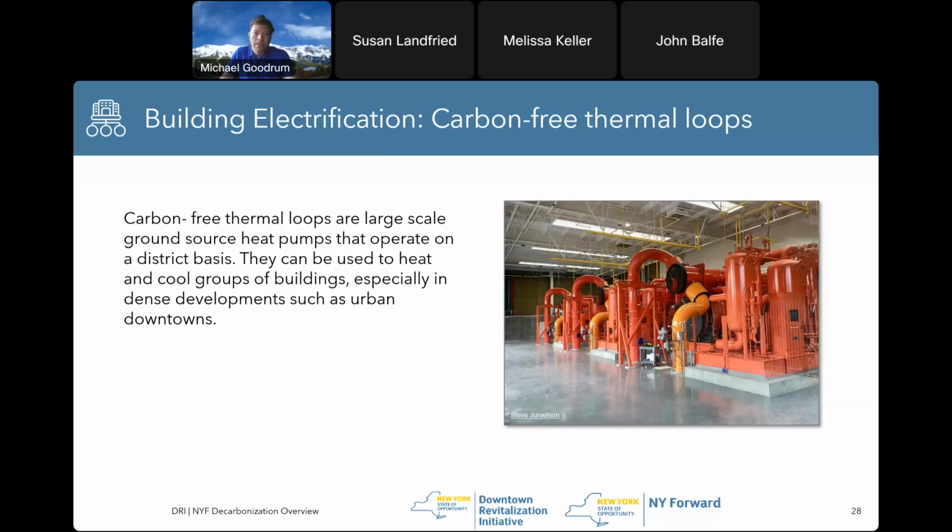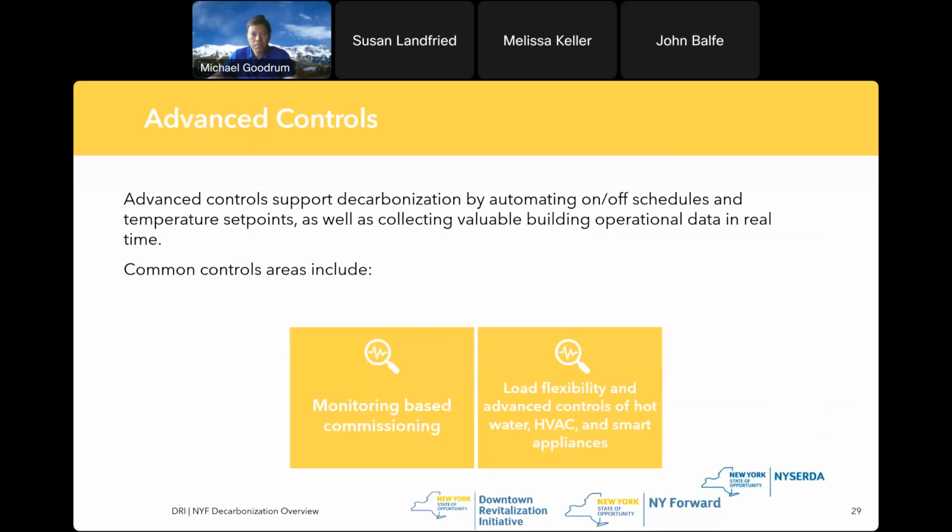I know I've seen some small towns that have even looked at it for their town centers, stuff like that. So they can be an interesting option. The thing with ground source heat pumps they are expensive because of the drilling and all that. So it's something to really evaluate before you just dive into ground source heat pumps, but it can be a really good option and a very efficient source of heating and cooling.